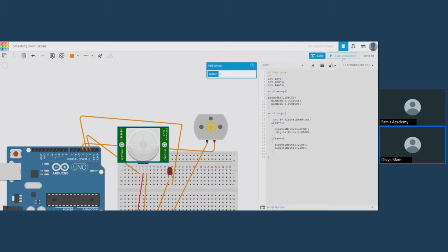Then you might ask me, how could we implement this in our home systems? How can we interface with our normal tube lights and fan motors at home? Here we are going to use the relay module. A relay module is nothing but an electronic switch. By using that, we can switch on 12V devices with a 5V signal from the Arduino Uno microcontroller.